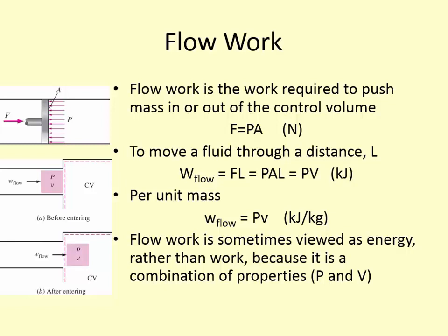So this force can be rewritten as pressure times area times L, whatever the distance is that we're moving it through. And we can combine these two terms, A and L, so the area times the distance will be equal to the volume. So the flow work is just the pressure times the volume. And per unit mass, it will be the pressure times the specific volume.